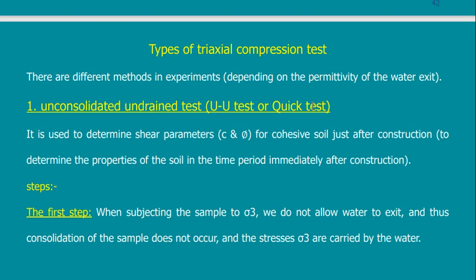So we call this the quick test because the taps are always closed. I just put water, then I add sigma, the stress of the piston, and the test is finished. And I just increase it till failure. I don't want to wait for water to leave. So this case resembles what? It resembles the case of clay with water at the early start of loading. I have soil with water, clay with water, and I put my load at time 0. This test resembles this case.